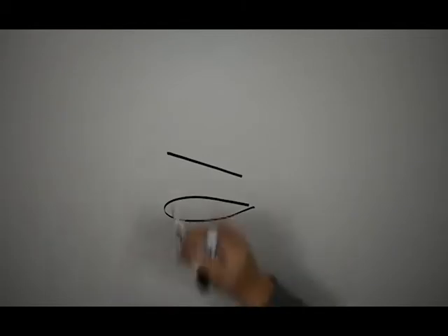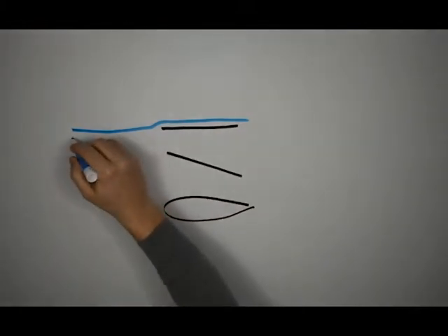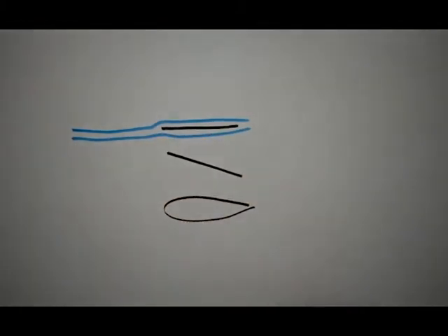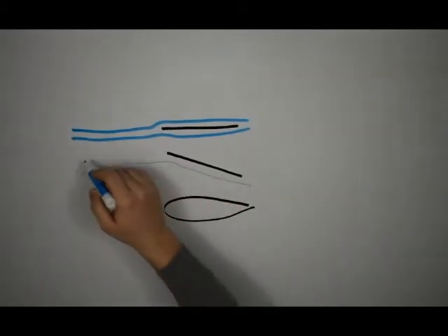Hypothetically speaking, you could use a flat plate. The problem with using a flat plate, though, is at 0 angle of incidence, it works just fine. The air flows over the top and bottom smoothly, and everyone's happy. But when you add some incidence to this, you have the air flowing nicely along the bottom where there's going to be high pressure.